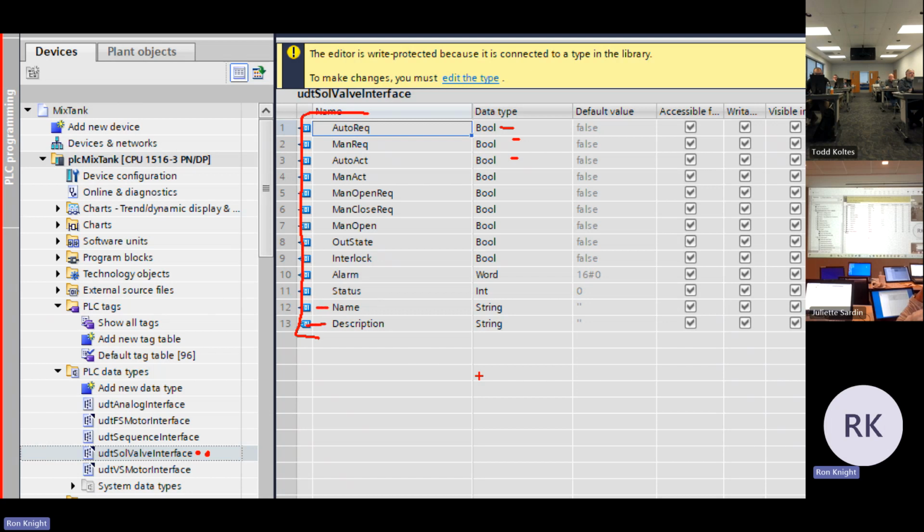And that is because the IEC said you shall have a Boolean data type. You shall have an integer. You shall have a string. Oh, and by the way, you're going to be able to wrap all those up into your own user-defined data type. All right, so Rockwell is embracing that IEC standard, as is Siemens. Again, we've got some additional columns out here. I'm going to go over those a little bit later.